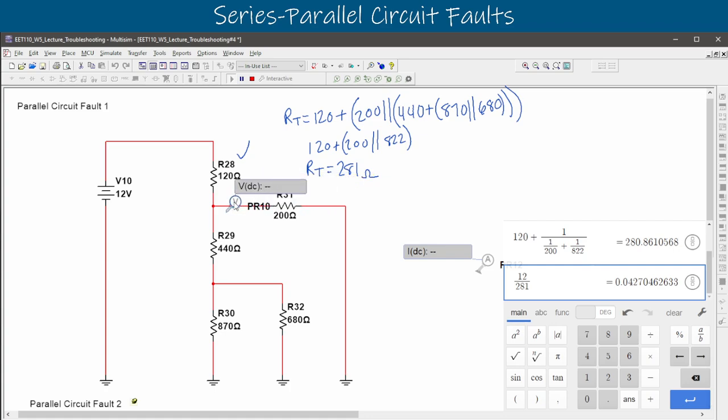So that's 0 volts at the bottom. And we see that 6.27 volts goes down towards that other branch there. So let's check our current. Let's make sure the current divided in the parallel branch here, because we know that it came down to 47.8 milliamps comes down, and we know that it should divide here. Some of it should go towards this one, and we get most of it towards this one. 31.3 milliamps out of the 47 goes towards this 200 ohm resistor.